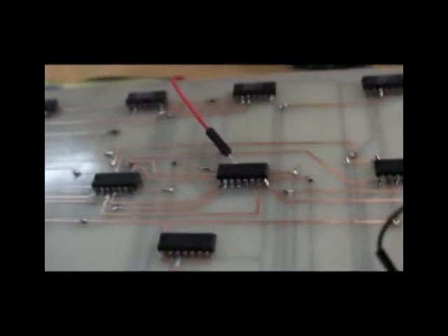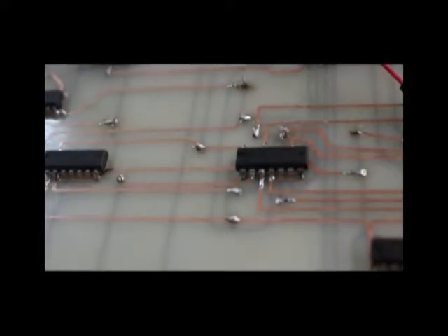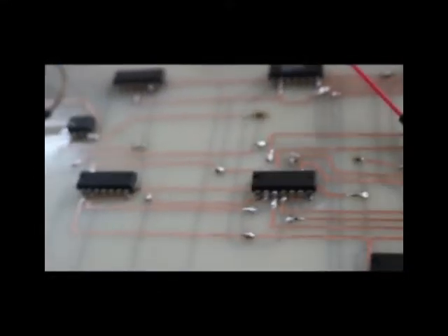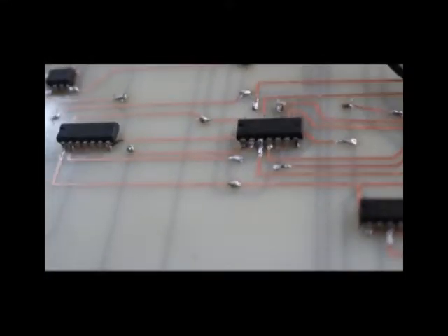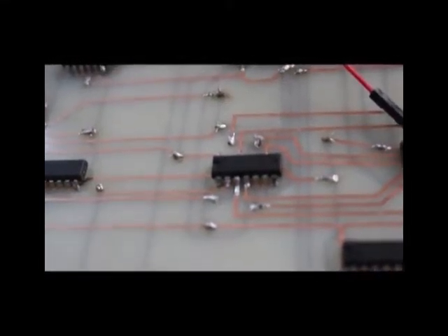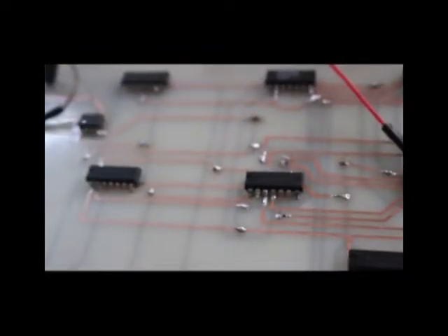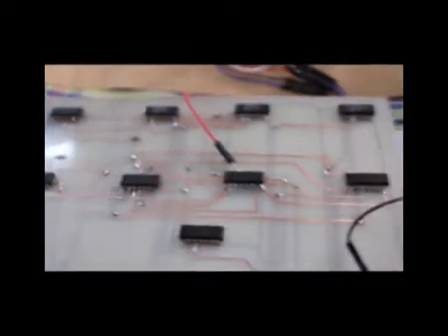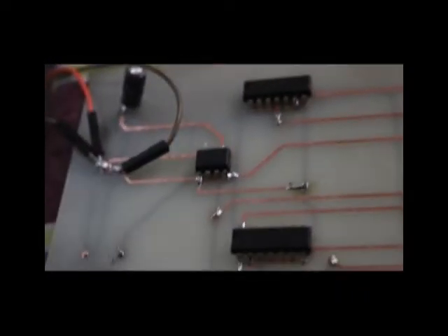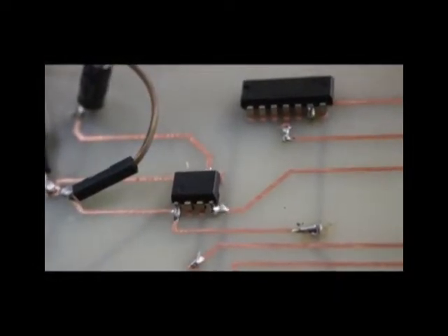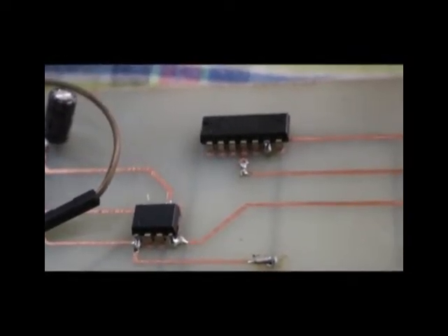and here is another 7447, and here is the 164 IC, which is the SIPO 8-bit register, and we divide it by 4-bit and 4-bit and send it to the 7447 display decoder. Here is our clock timer IC. We send the clock pulse around 1.5 seconds.